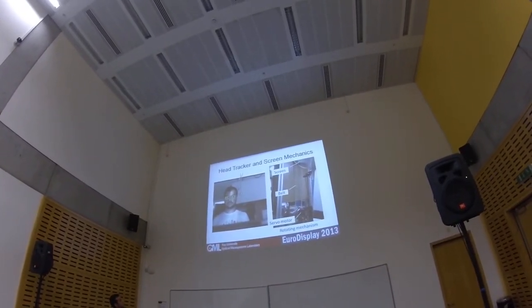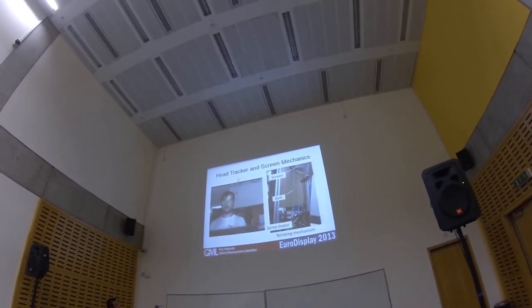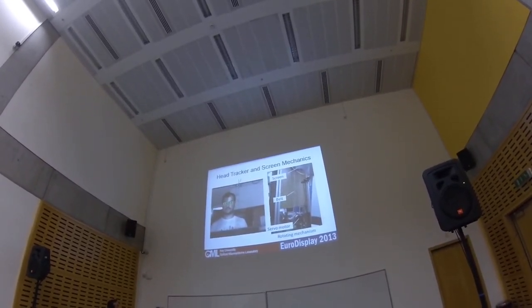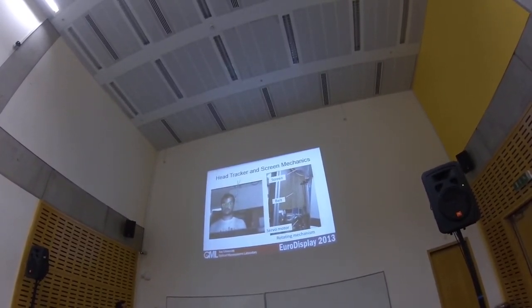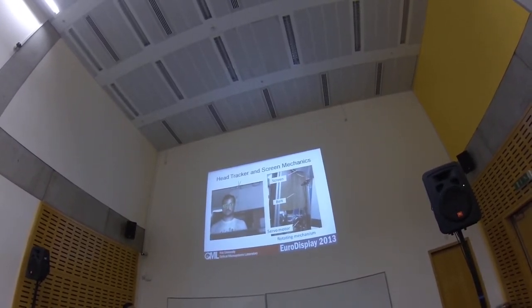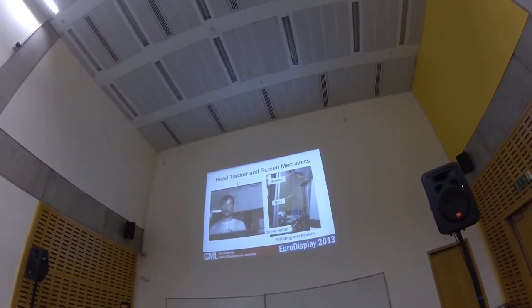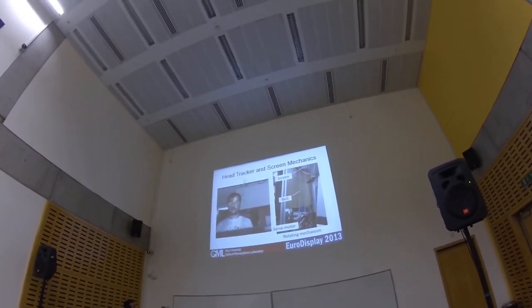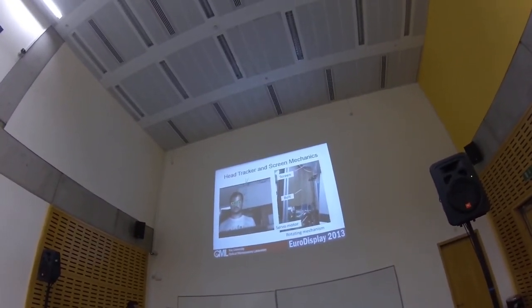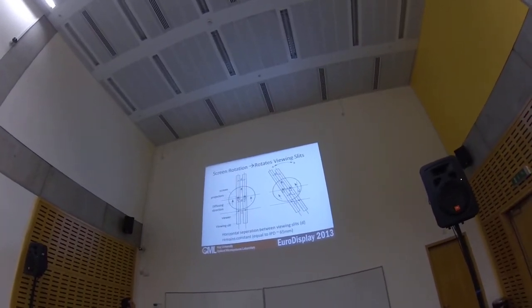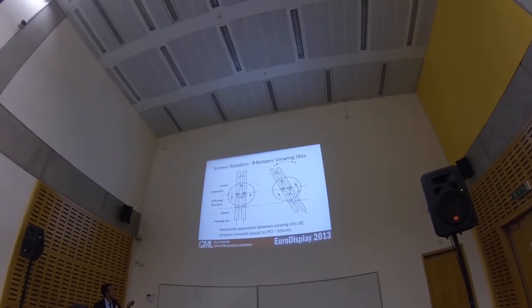So when we know the position of the viewer and the position of the projectors, we can know the angle with the vertical line, so that we can rotate the screen by that angle. And how we rotate: we have a servo motor which is connected to the screen by a gear belt. So by the information obtained from the webcam, from the position of the viewer, we rotate the servo motor and the screen. And this is how we move the viewing slits, explained in a schematic.